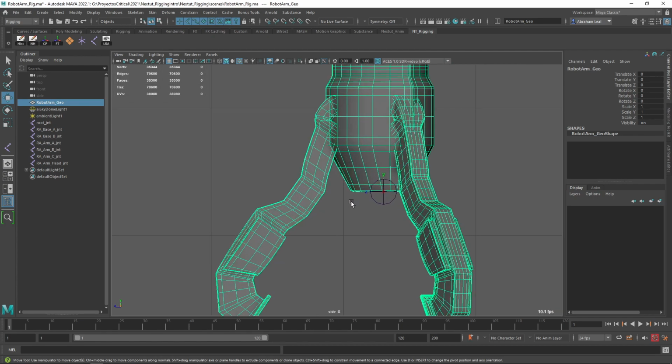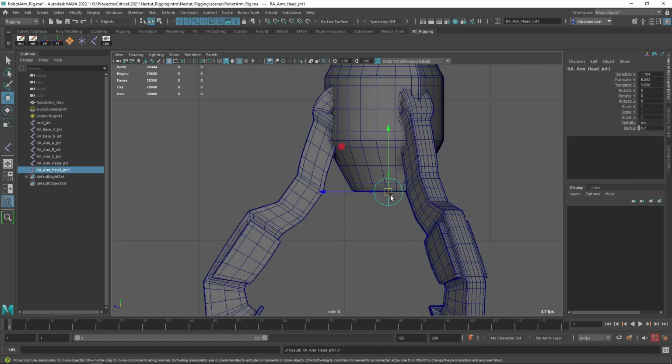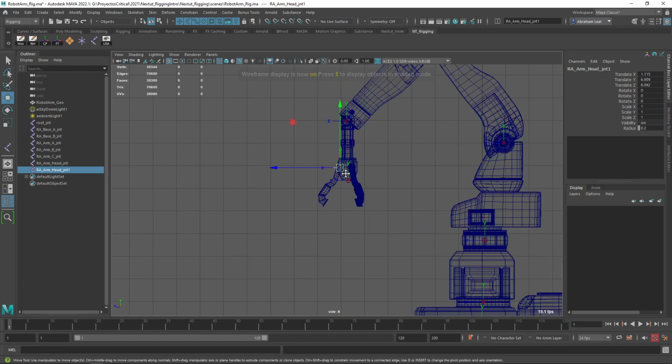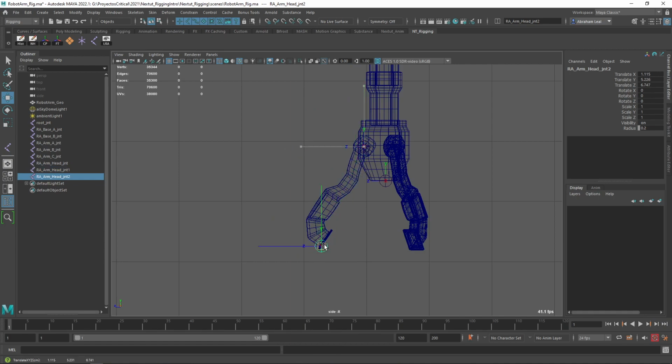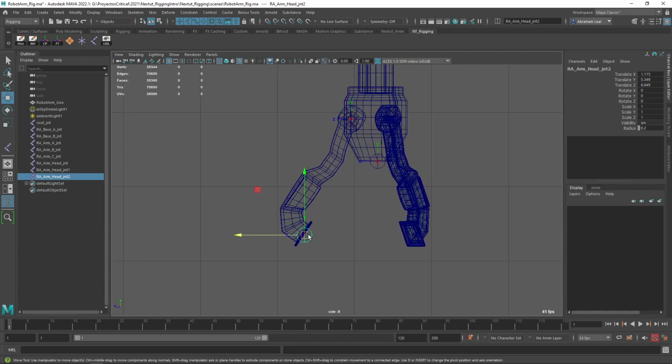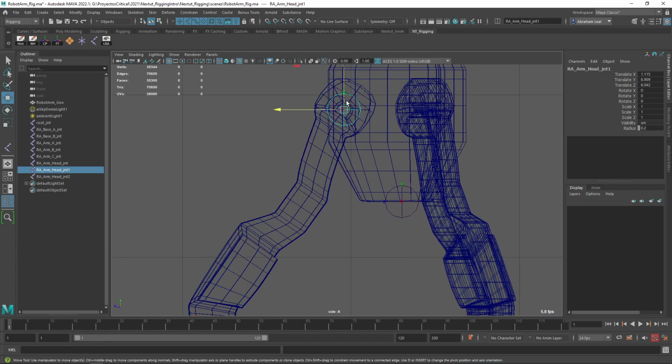I'm gonna go here, and this first leg is probably the easiest one, so I'm just gonna Control D, and move it. There's no pivot points. I'm just gonna move it there on the center like that. And then I'm gonna duplicate this one and position it on the tip here. The only reason I want to position it on the tip is for visual sake, because these tips are not gonna be moving anything. The main important bones are gonna be these ones up here. So let's call this finger A underscore joint, and then the one that we copy is gonna be finger A tip underscore joint.